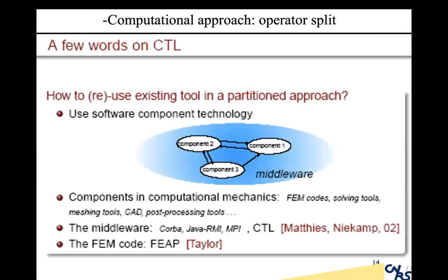Of course, that's a lot of computation. That's the one that you can do. Basically, the idea that we used was this coupling: you take software for one component, software for another component, and you simply couple them in terms of these joints. And then you have operator splitting, how you actually split up the computation, where you handle this joint in order to keep this computation stable.